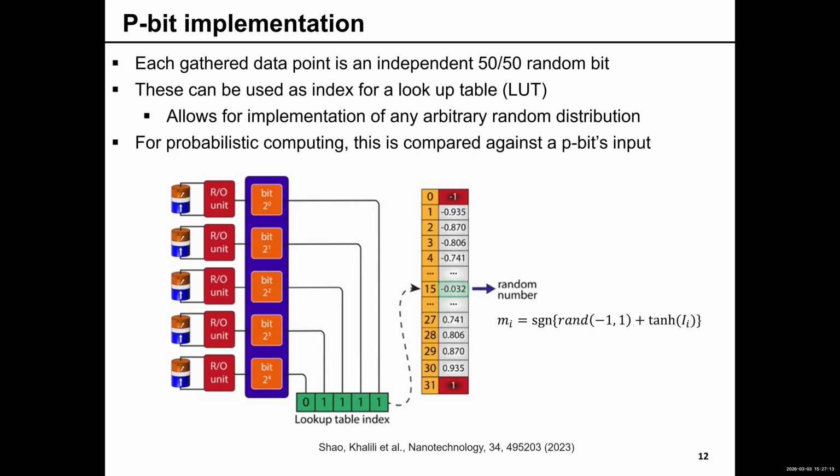What we found was that this is not necessarily a big problem. As I indicated a couple of slides ago, we don't really think the tunability of the probability at the device level is a strength of magnetic tunnel junctions, precisely because it comes with this requirement to have individual calibration for each device. And so instead, what we decided to do with these devices was to really use them as coin flip devices.